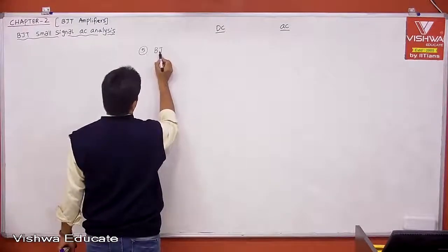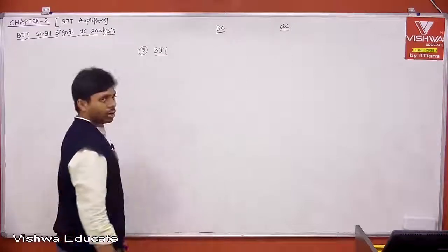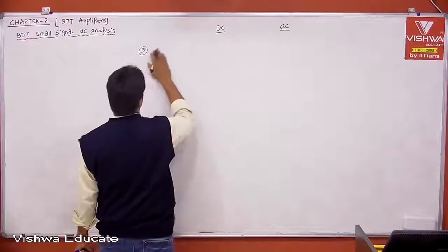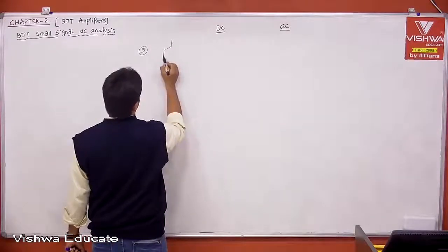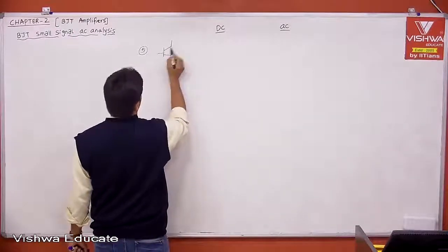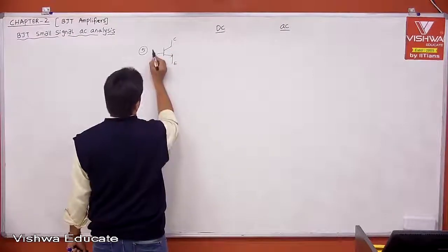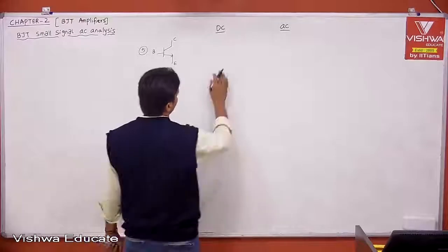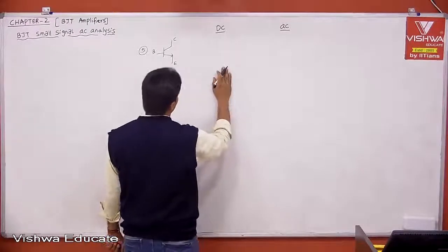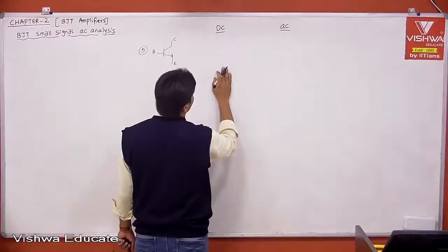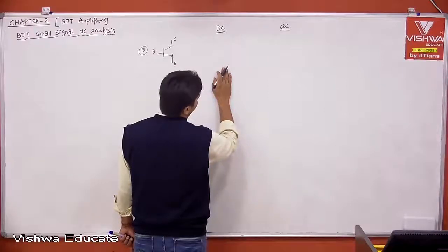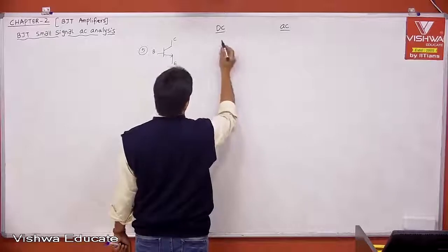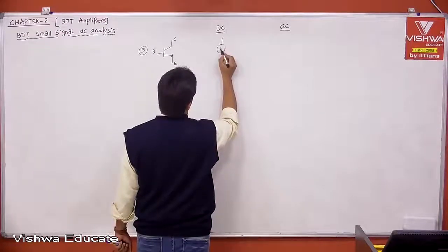BJT. Okay, let us take only the ideal model, that is enough because this is bigger. Now the BJT is nothing but the symbol, right? This is collector, emitter, base. Now what is this? This is what we are representing with a current source, right? Therefore, what is that current source? If you take the ideal model, the current source is represented between collector and emitter.